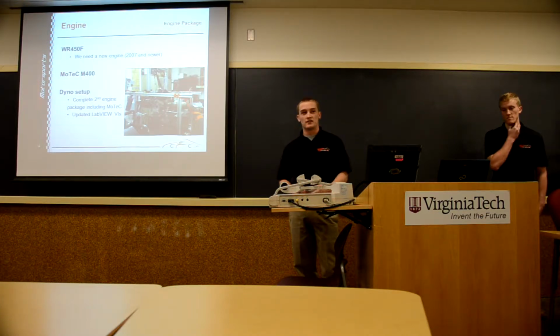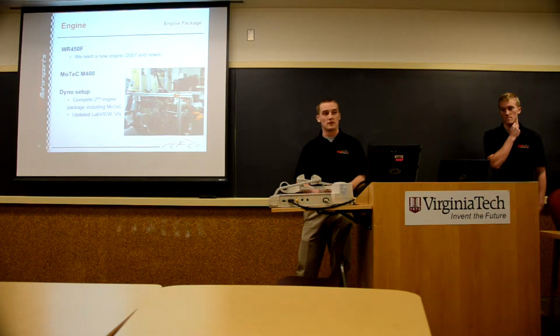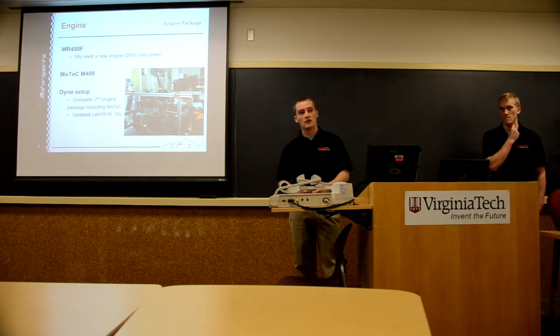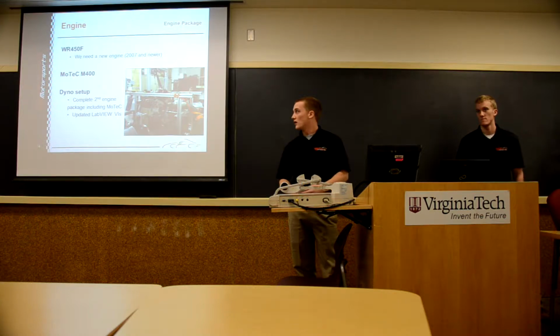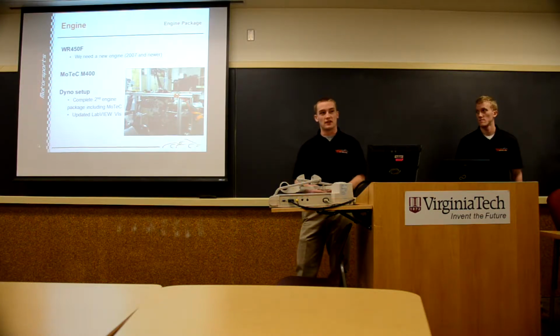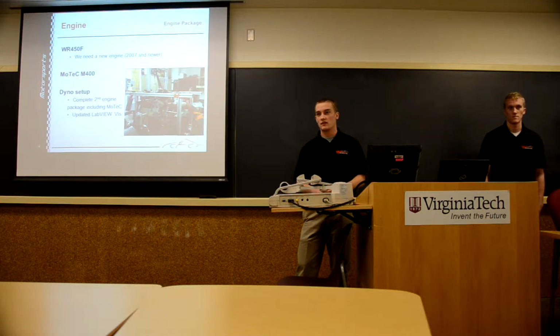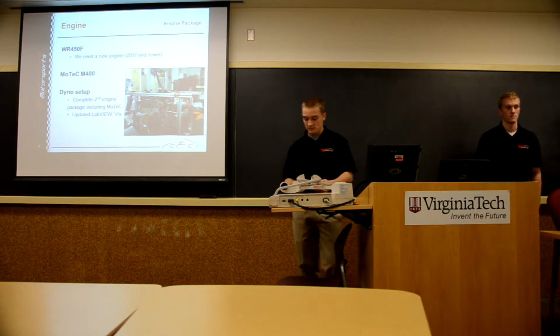We've made great advances in the dyno this year, and we're going to continue to do that. We have the whole dyno room to ourselves now. The electrical system has helped us clean up the wiring. We plan on having, in the next couple weeks, updated LabVIEW VIs to help us out with the software. We'll have a complete second engine package set up in the dyno that will be modeled exactly as it will be on the car. We'll have identical geometries on the runners and identical connections and links in the wiring.